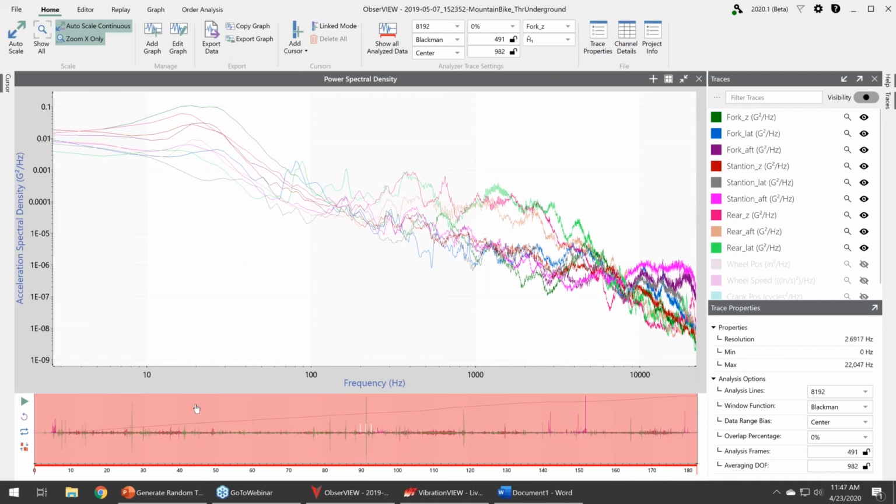So we are aligning that data via the timestamp. The best way to do that with the GoPro is to connect to it with your phone, and you can sync the time data with your phone time. You can also sync your Observer 1000, our data acquisition time, with your phone time via our VR mobile application that runs in the Observer 1000. So it's all time synchronization based on timestamp of the data.